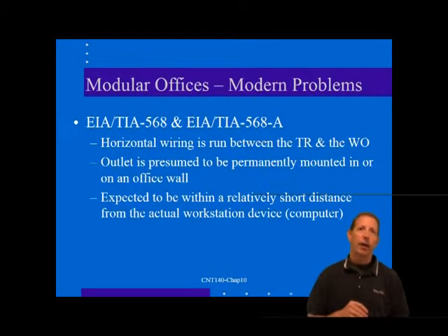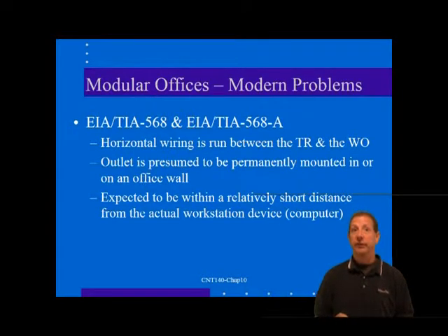The significant cabling problem that occurs with the use of modular offices is that the modules can be easily rearranged. Furniture modules are very easy to move about. The modules simply unbolt the same way they are originally bolted together, and then they're moved as needed to reconfigure the office to meet new personnel requirements. In most of these modular furniture systems, electrical connections either snap together as the modules are joined, or they're easily cabled out and extended by a system of plugs and receptacles. Unfortunately, the communications wiring, including our LAN wiring, must be painstakingly removed and rerouted into the new furniture layout.